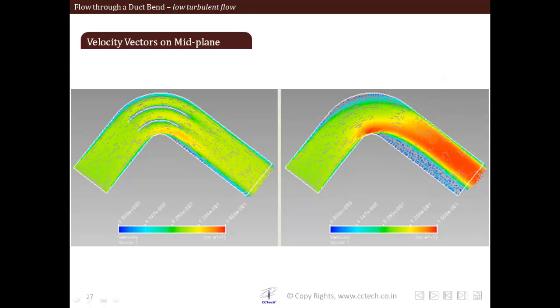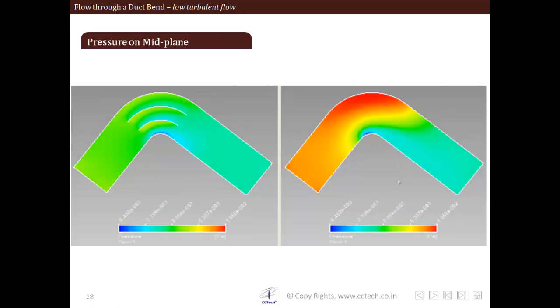As you can see, the flow separation is drastically reduced with guide vanes. We have more uniform flow going through each vane section, and this particular high velocity spot is reduced. When we look at pressure, this high pressure spot is drastically reduced, so this improves stability of the structure as well. And this flow separation is also reduced when we introduce the guide vanes.